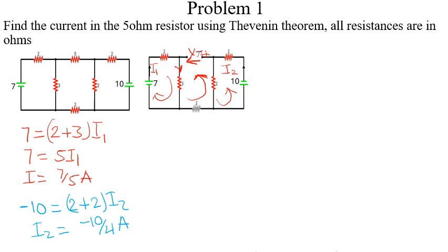So we said sum of voltage sources is equals to sum of voltage drops. When we are going in the anti-clockwise direction, and VTH is also going in the anti-clockwise direction, VTH is equals to 3I1, and I2 is going in the opposite direction. You see the arrow I2 here, I2 is coming down here and we are going in the opposite direction, so we have to negate it. So it now becomes minus 2I2.